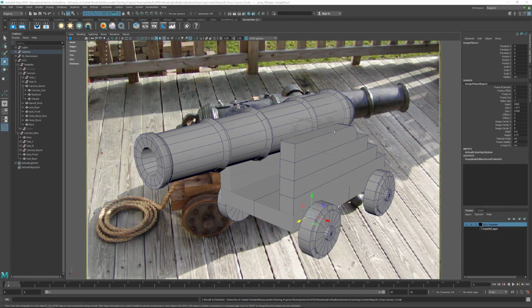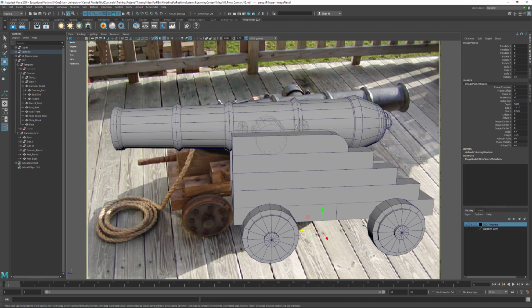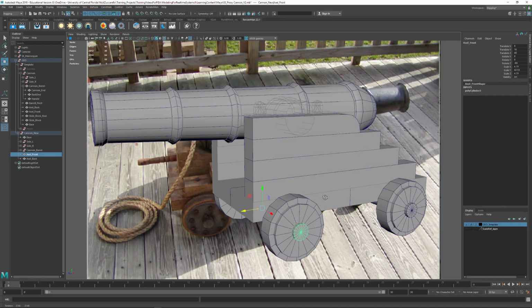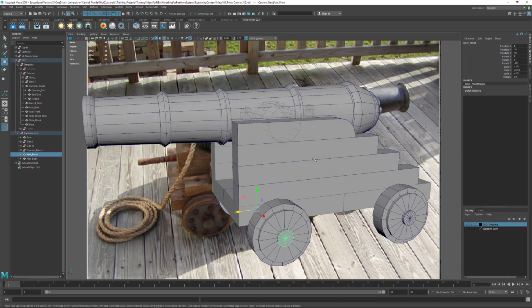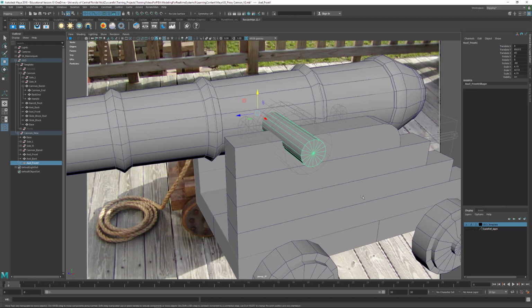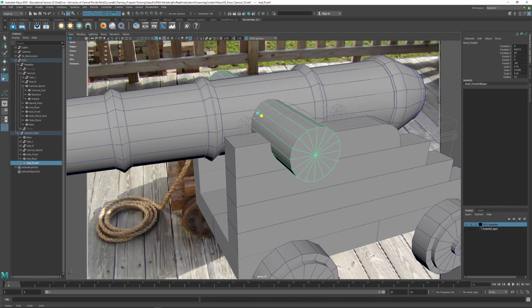All right, for the cannon, let's go ahead and make this pivot that you see within here, so the cannon could actually rotate and angle up or down based off of this pivot point that you see here. We've already got an axle or some kind of cylinder that's working in this space, so we can just duplicate that, hit Control D, and move this thing up. We'll scale it up right about there, and then scale it this way. We don't need to be super perfect.